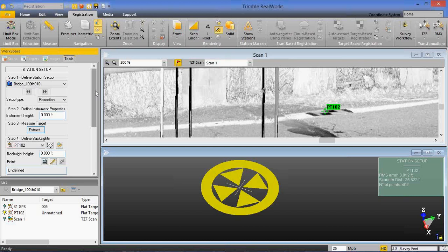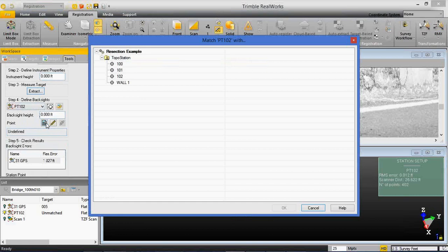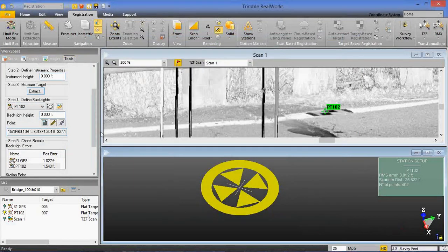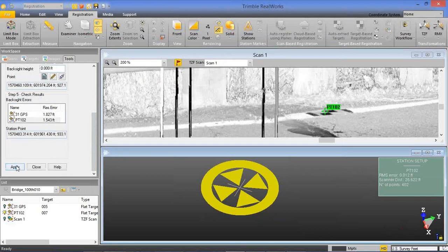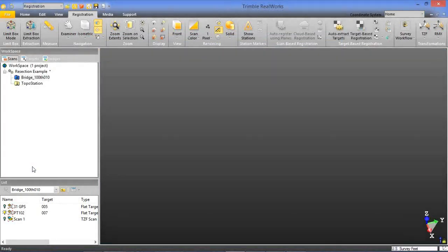I was thinking of ways that this would help crews out in the field. The typical way to get your scans on a coordinate system is you'd have to have a crew come out, set targets, and then direct reflex coordinates onto all the targets, and then come and scan everything. Here, one crew can come out and scan everything and establish coordinates at the same time without having to make two trips. Yep, I agree.